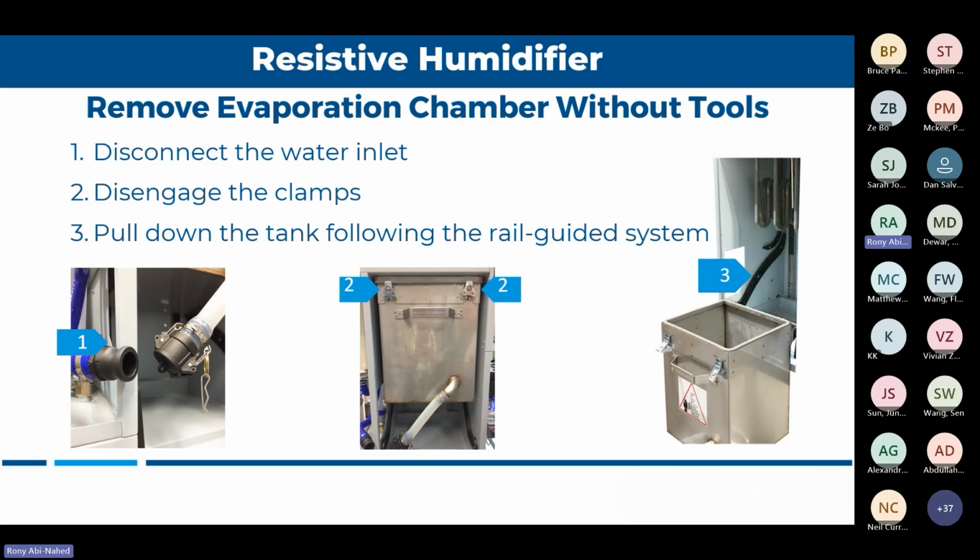And there's a bunch of brands in the market for this type of unit. Depending on what brand you're using, some are harder to get access to the tank to clean. Some are easy to get access to, like the one I'm showing here. It's very simple. You just disconnect the water inlets, you slide your tank. Usually all the scale is inside this tank. So you take the tank out, you clean it, put it back in, slide it back up, you're good to go.